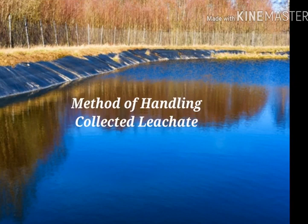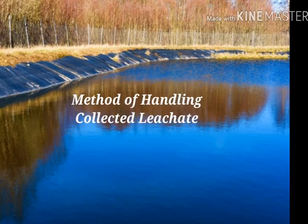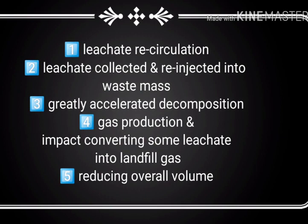Method of leachate management. Re-injection into landfill. One method of leachate management that was more common in uncontained sites was leachate recirculation, in which leachate was collected and re-injected into the waste mass. This process greatly accelerated decomposition and therefore gas production, and had the impact of converting some leachate volume into landfill gas and reducing the overall volume of leachate for disposal. However, it also tended to increase substantially the concentration of contaminated materials, making it a more difficult waste to treat.